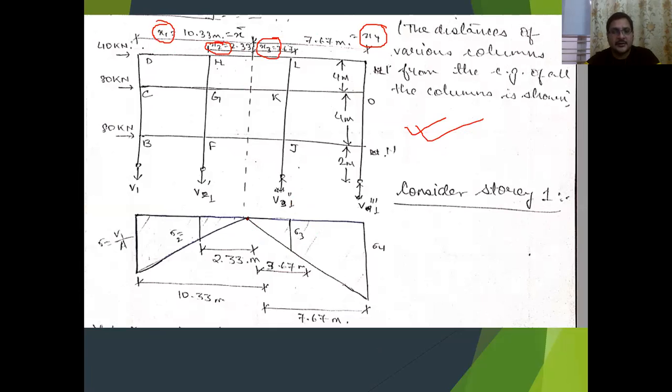From the second assumption, the concept of proportionality, the stresses acting at each and every column will be proportional to the distance of that specific column with respect to the CG. That means the stress at column 2 will be proportional to its distance from the CG. Using that proportionality concept, we can draw similarity triangles.